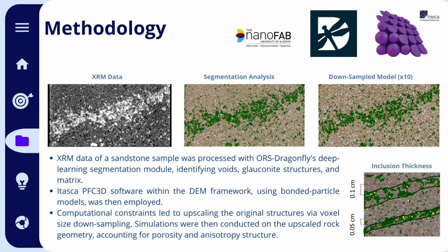As part of our methodology, we used X-ray microscopic data to examine a sandstone sample using the deep learning segmentation module of ORS Dragonfly software. Through this analysis, we were able to identify both the voids and glauconite structures within the sample. These findings were then used as inputs for our numerical modeling, for which we use the Itasca PFC3D software. The model is built within the discrete element method framework and utilizes a bonded particle model.